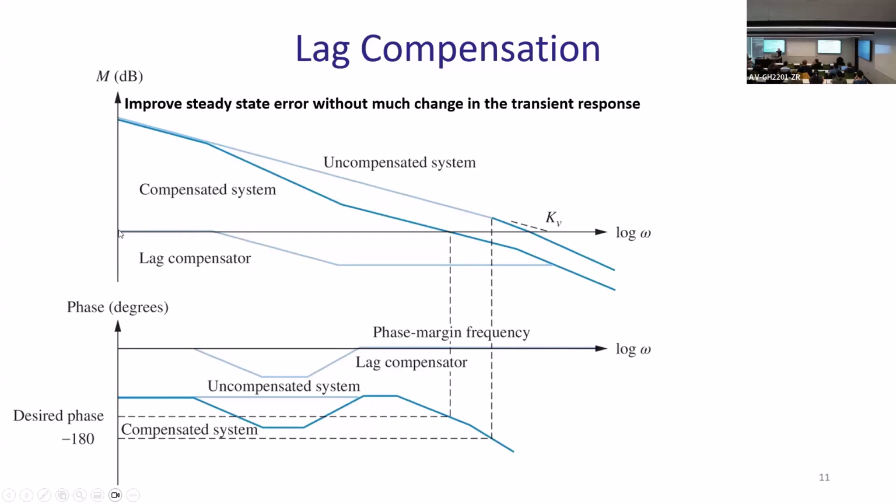And here you will not touch that point at all. Okay? So this will stay wherever you want it to be. You will not pull it down really. You will keep it where it is, because the gain of the controller looks like that. It's going down with frequency. So you highlighted the lower frequencies where you want it to be high, and you made it constant at higher frequencies where you don't want to touch anything. All right. This was the idea of lag.